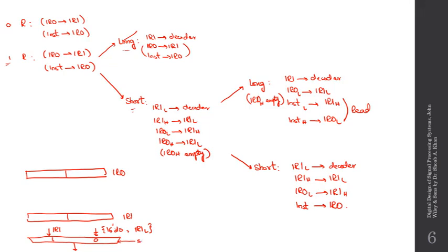So we'll have a select, let's say we call it select 0. This is the select signal that will be controlling which instruction is currently being executed or which instruction is going to be executed. In a similar manner, we'll be requiring muxes for every sub-register available in our design. Meaning, coming here to IR1's lower part, we'll be requiring a mux here.